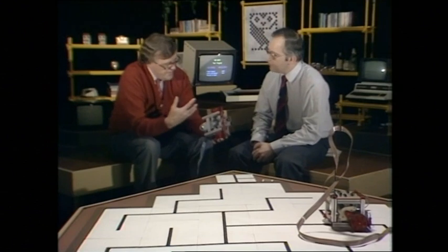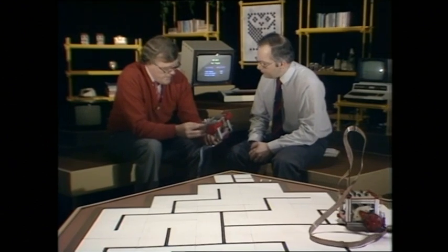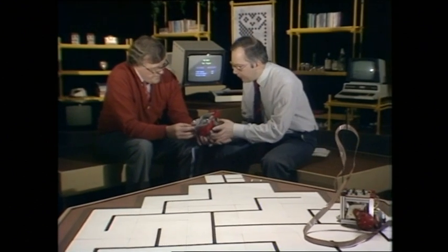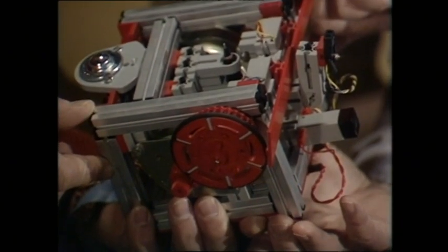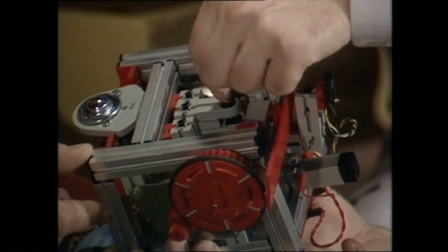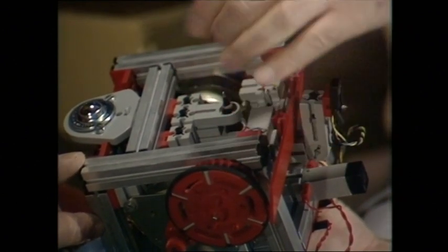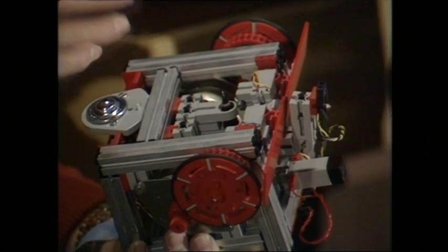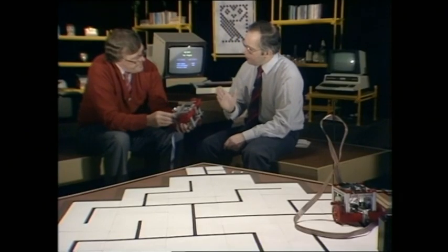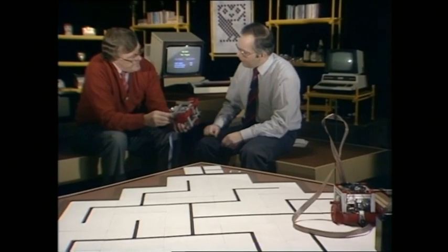Well, those are the input devices, and we've also got some output devices here. Right, well, we've got two output devices. There's a stepper motor here and a stepper motor over here, and as well as that, there's a device for moving the pen up and down. So, stepper motors and pen up, down. The stepper motor just moves it round one click at a time at about 7.5 degrees. When you give it one digital pulse, it moves, as you say, a very small angle.